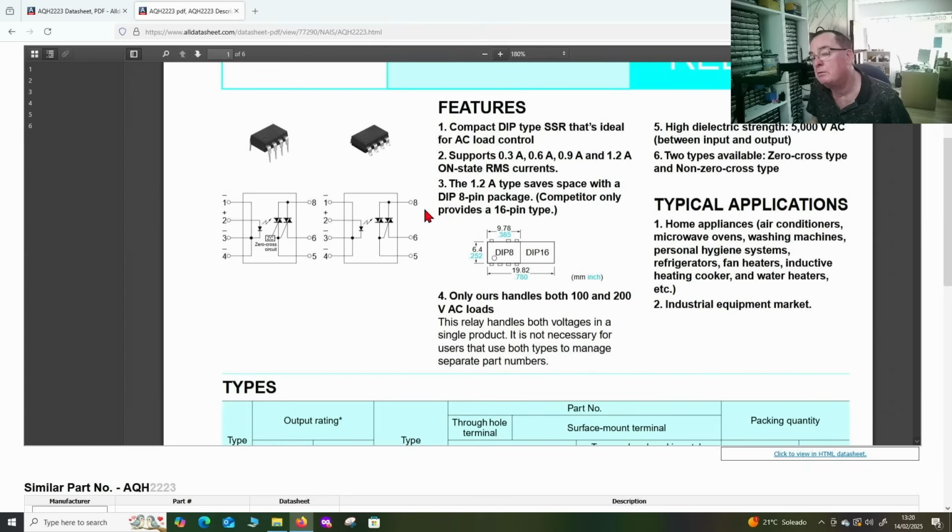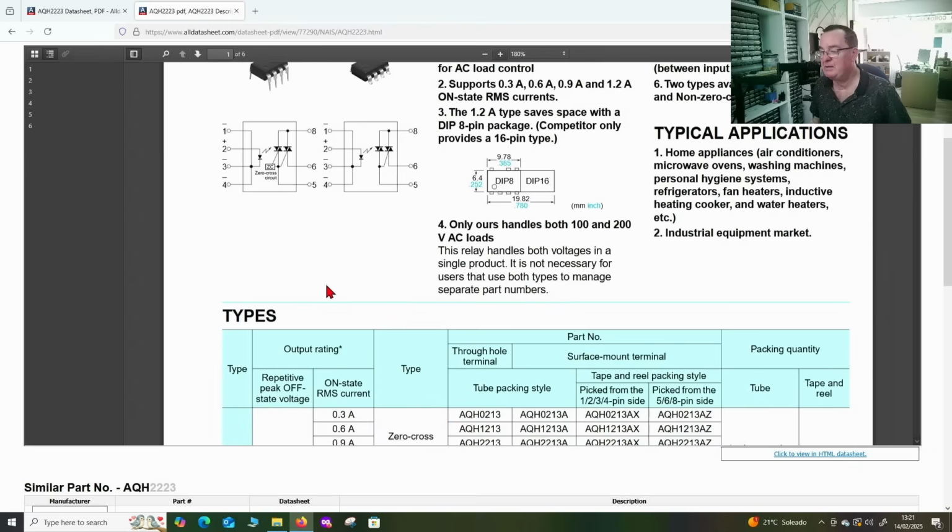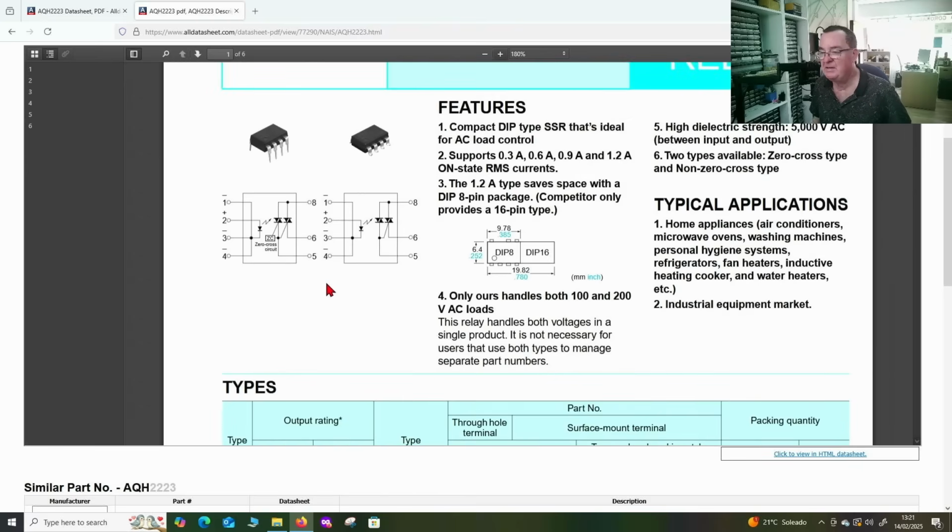And it looks like it either switches pin 8 to 6 or 5. So, yeah, we could test that, but we'd have to test it out of circuit, effectively by lighting the LED and putting in AC voltage with a load here and then see if it switches or not. So we could test it, but I don't see easily in circuit how we test it, okay? Without this thing connected to whatever it connects to. We can certainly check if the LED is okay.